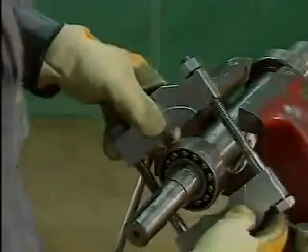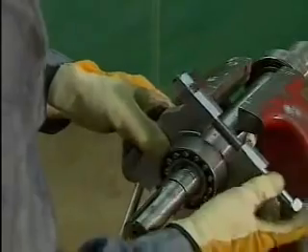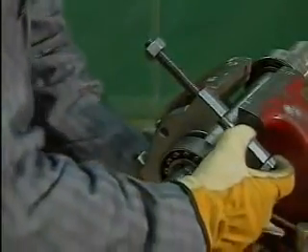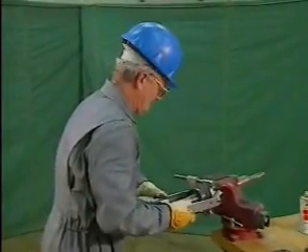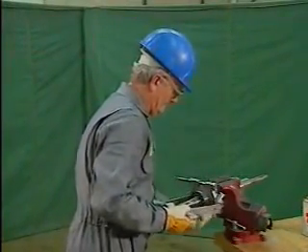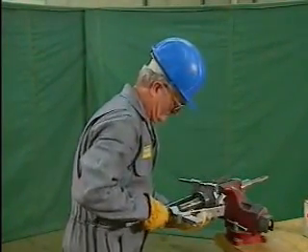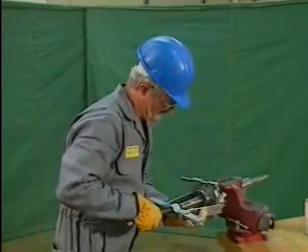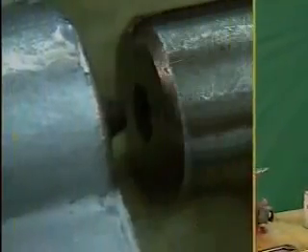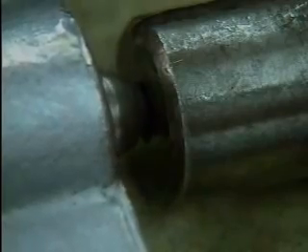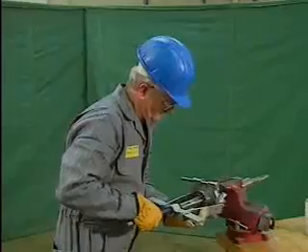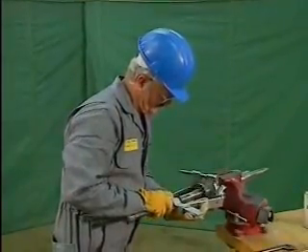Then he sets up the bearing puller jaws behind the bearing so that they rest loosely against the shaft. Next, the mechanic hooks the side rods behind the jaws. Then he makes certain that both rods are aligned correctly on the strong back. In this example, the mechanic places the lead screw into an alignment hole in the shaft. Then he tightens the lead screw.